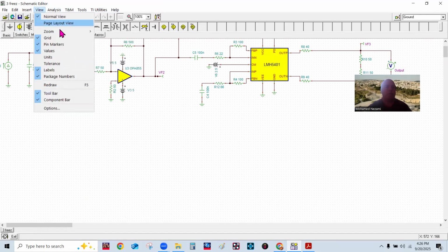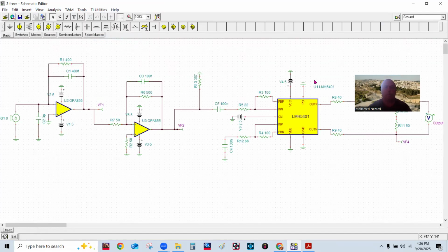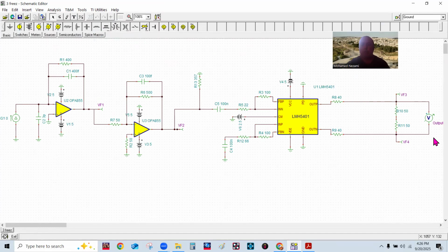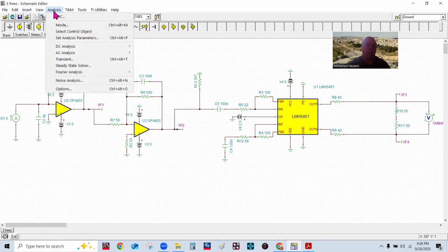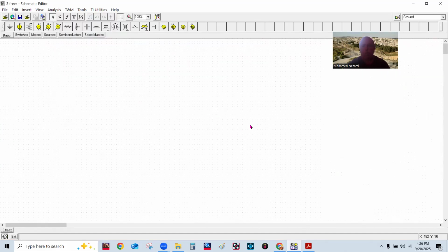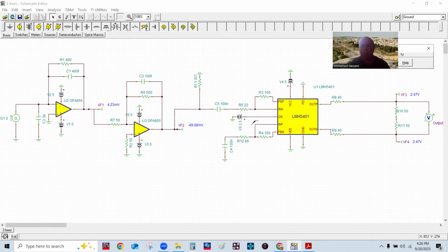Okay, so this is what I did. I have my ADC input assumed to be like this here, without any parasitic capacitances. And I took this device and interfaced it to my other amplifier, my TIA that was designed in part one of this series. So first of all, I want to see my DC points. I've got 2.4 volts in here, and of course this is negated from this because this is an inverting device.